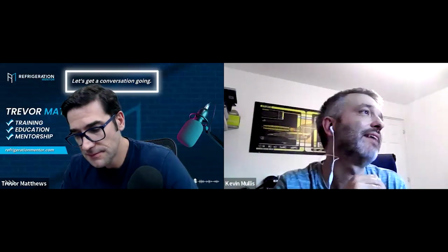No, it doesn't close the valve instantly. It just stops it opening anymore. So it will stick at the percentage it's at. Yeah, the question the person asked was, does the MOP close the valve? So it'll stop at that. And I know on the Copeland or Alco ones, or the Dixell controller, it would stop at that point, and then it'll close 10% per second, depending on how you set it up, until it stays at that pressure. So it depends on the controller. Initially they all work like an MOP expansion valve would have worked back in the day. It will just sit where it is.